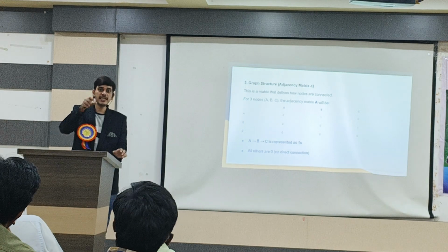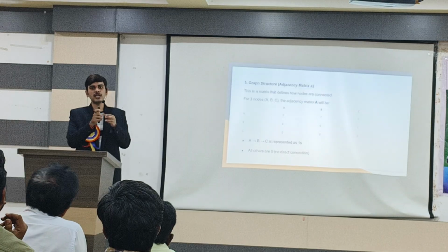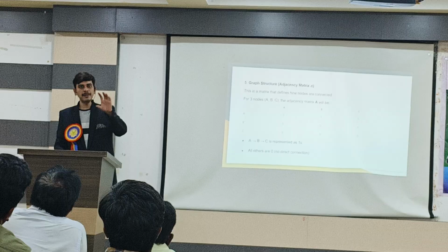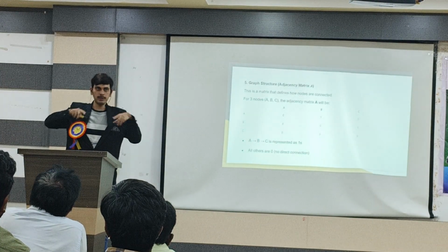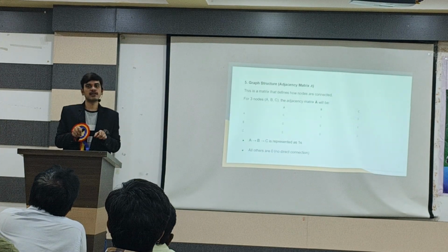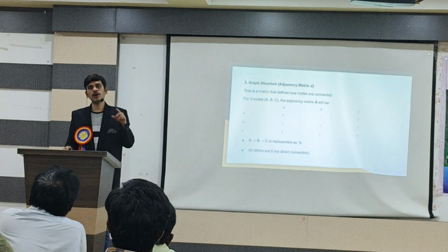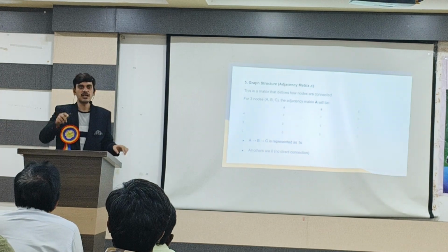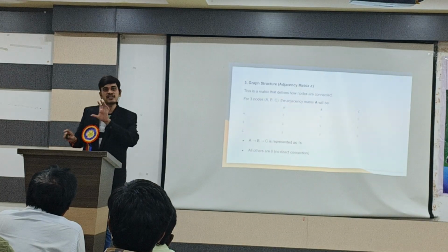Internally there are macros, cells, everything. Initially, these macros are placed. Macros are hard IPs; IPs are different and logic cells are different. They place the IPs around the boundary of the block because the logic cells will be interacting with the macros. If you placed them at the center, you couldn't place the logic cells. Initially they place around the boundary, and we look at the fly length. Fly lines are connections: a node is there, how many connections does it have? Based on that, they do the initial placement.